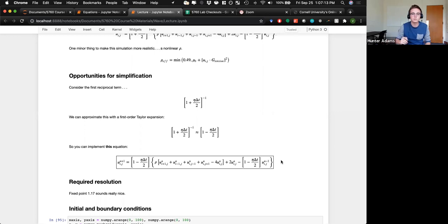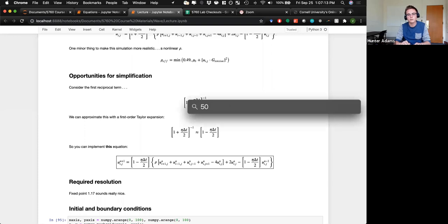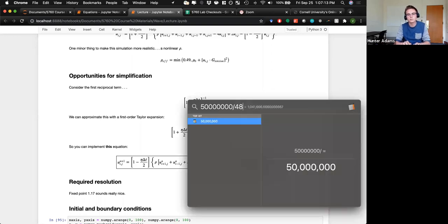So let's suppose that you're using the clock 50 line to clock your state machine. You have a 50 megahertz clock, and suppose that you are able to update a particular node in 2 cycles. Well, if you have a 50 megahertz clock, 50 million, and you're sampling at 48 kilohertz, that means there's right about 1040, 1041 cycles of the FPGA between each audio sample.